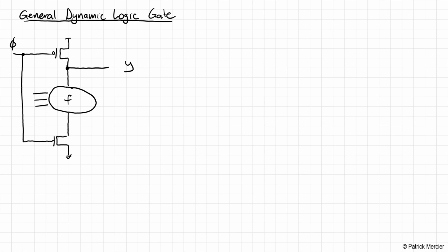Now, the logical inputs are given into this function f here. Okay, so what's going on here? First of all, let's call this function f. This is actually going to be the same pull-down network as before. If we know how to design a pull-down network in static complementary CMOS logic, this will be exactly that, except only the pull-down, not the pull-up.